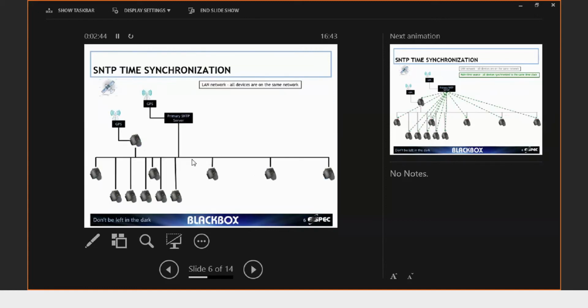Now, next, as I explained, you can use the device itself, the G4K, as a time server. The device has an internal clock, or can get an external GPS time. As also explained, the GPS can provide time synchronization only for one unit because it's a serial RS232 cable.